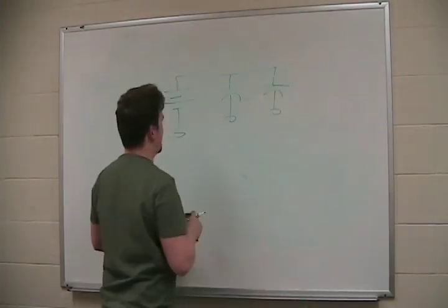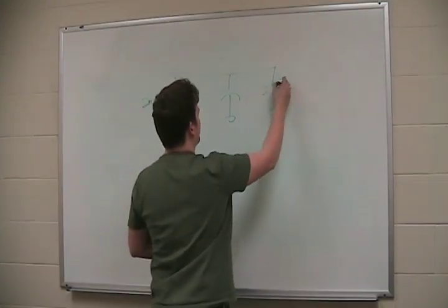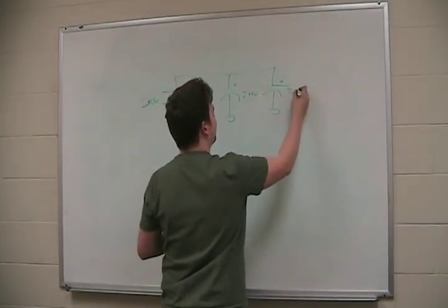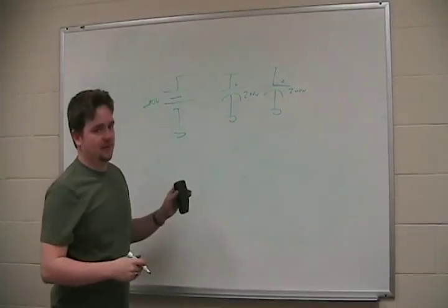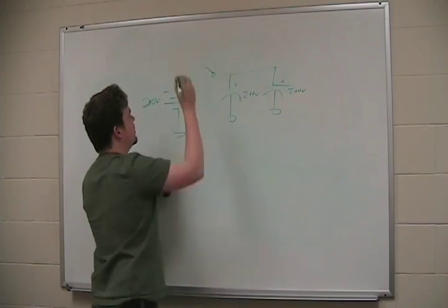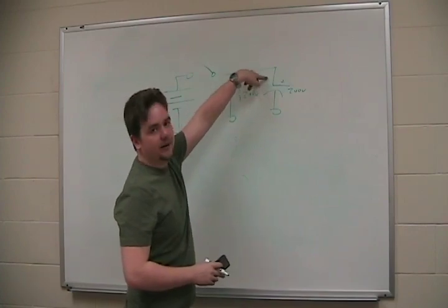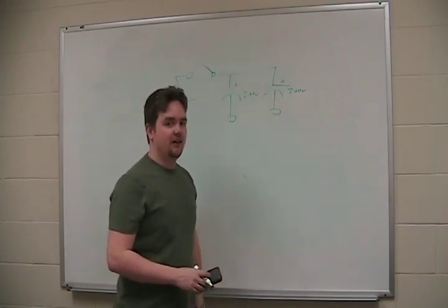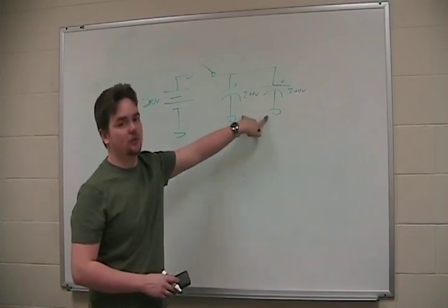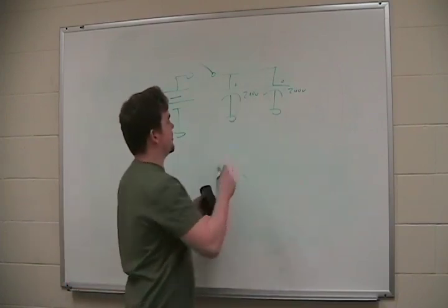Say I want to charge up these capacitors. Remember, all these grounds are connected. I just want to charge up all these capacitors to, let's say, 200 volts, the 200 volt capacitors. So I'm not exceeding the limit, but as soon as I remove the power from the circuit, all the electrons stored up here at 200 volts are going to stay there. It's not going to supply more than 200 volts, because remember, they're in parallel. Same voltage, twice the current. If I added another one in there,